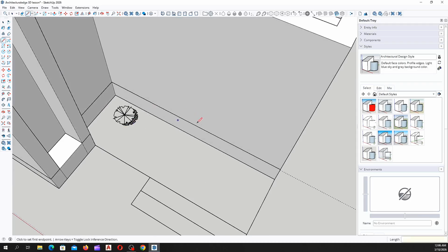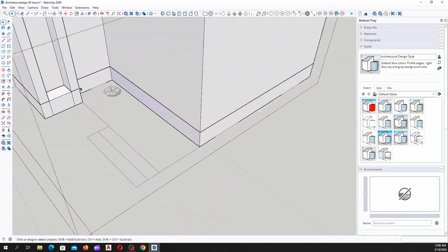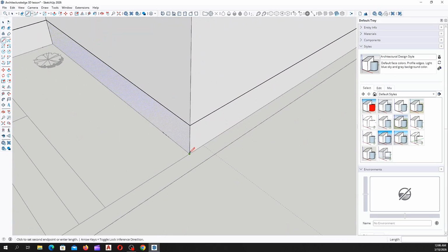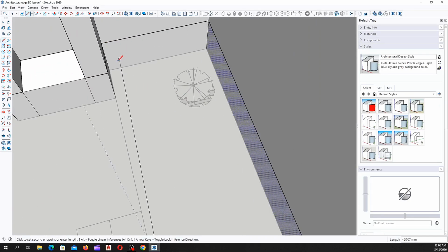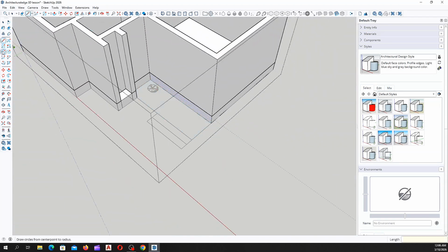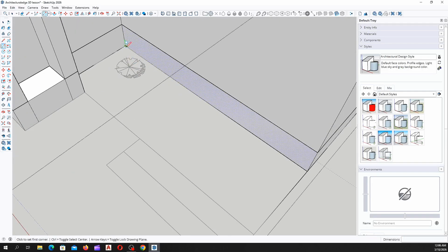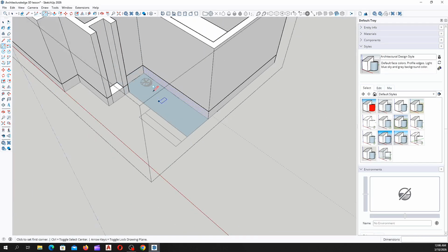So, all right, before then, let's move back into our model. So we'll map out the foundation of our veranda this way. You can use this tool, your line tool, or you can use your right angle tool. What I just did, I tap my Ctrl Z to undo what I did with the line tool. So now you pick your right angle tool, then you can pick from this angle here and you extend, you snap to this angle.